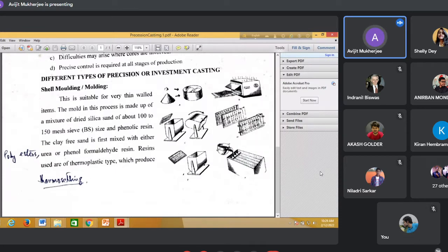So now heat the job, that is the pattern. You prepare a pattern using a very fine material like copper or aluminium or any other material, a master pattern, that is the replica. So preheat that pattern. What is the desired temperature? After some time we shall mention. But the overall process is, this is the pattern, and this is now placed in an oven.